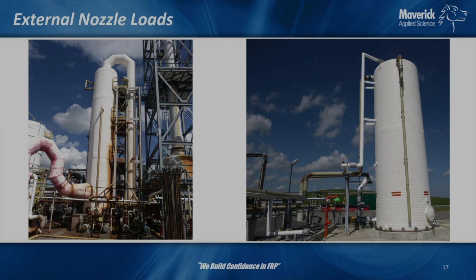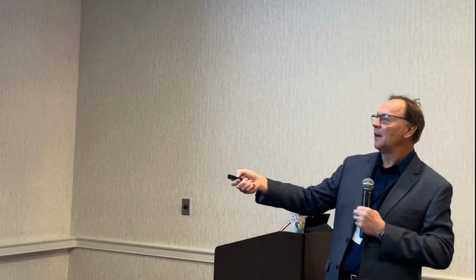And here you've got kind of the same thing where you've got a filament wound pipe, you've got FRP pipes here. Not sure, these could be centrifugally cast pipe. I'm kind of thinking that might be just by the look of the pipe. So that's got a whole different coefficient as well running up. But here you've got all this pipe here, and there's no anchor points here.